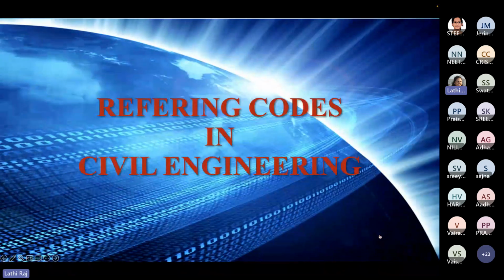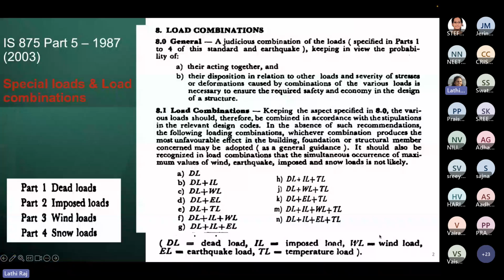If you see the combination of loads, this is IS 875 part 5, special loads and load combinations. You can see that it gives you the load combinations. Again, it is not exhaustive. There are other combinations also. But these are the minimum combinations you should do while doing a design. So, dead load plus imposed load, dead load plus wind load, earthquake load, temperature loads. These are the combinations you should do.